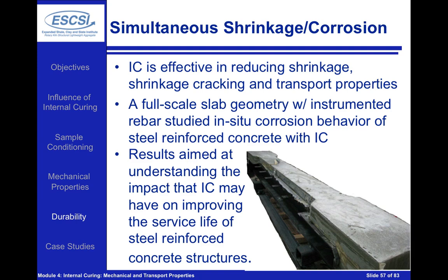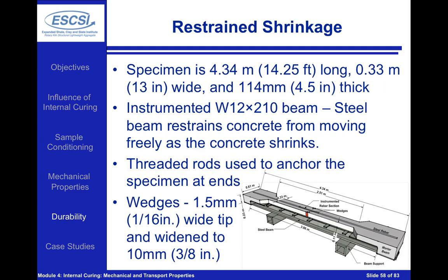This is a 15-foot long slab that was instrumented with a rebar that was monitoring the corrosion behavior, and the idea was to really try to couple together the big benefits of internal curing that we see. The first is we're going to reduce the shrinkage and reduce the potential for cracks that form. The second is we're going to get an additional benefit and reduction in transport properties, but it's really the combination of these that have the potential to improve the overall service life of our concrete.